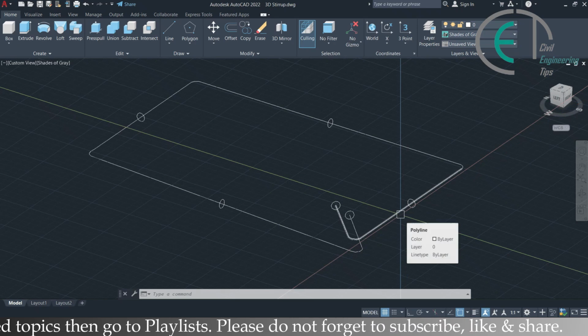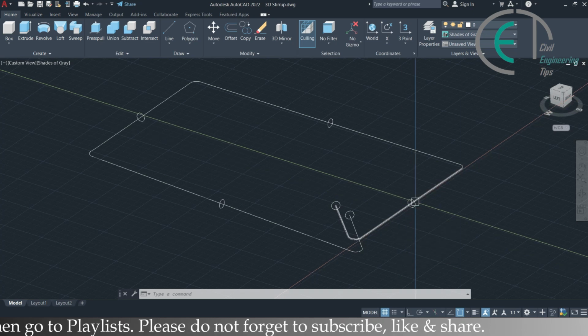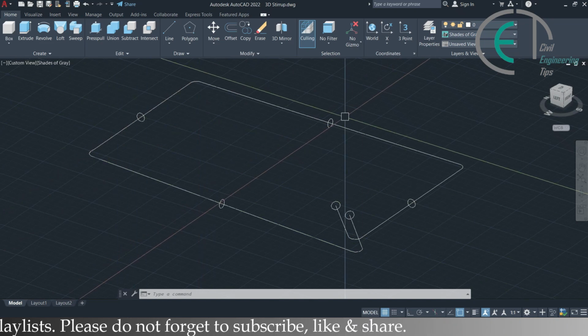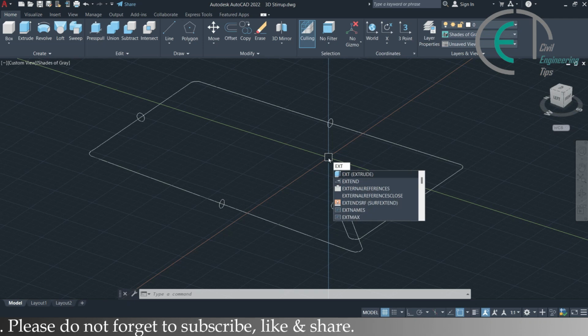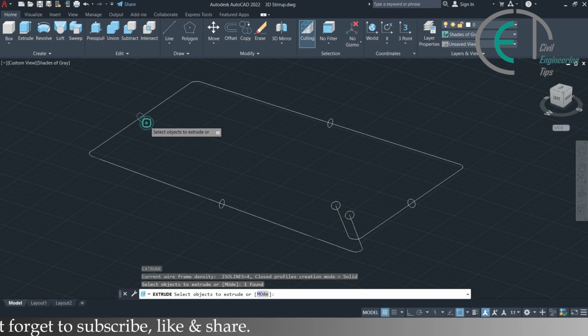Similarly we can make this a single line, but it is already a single line, we don't need to do that. And we can see that we can perform extrude command to these lines and use these circles. To do that, let's type ext to activate the extrude command. I'm typing ext, then pressing enter to activate the extrude command, and I am selecting the circle here.